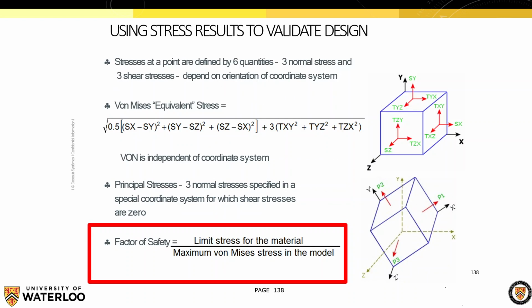This is really the only theory slide that I'm going to give you. The rest of it is a little bit mathematical. You might remember the way that three-dimensional stress state works. A lot of you might remember that in simple tension and compression, the stress is really straightforward to calculate. It's just a force intensity, meaning force over the area. What happens when you have complex shapes that you want to analyze in a real world situation where there's tension, compression, shear, all of these things combined?